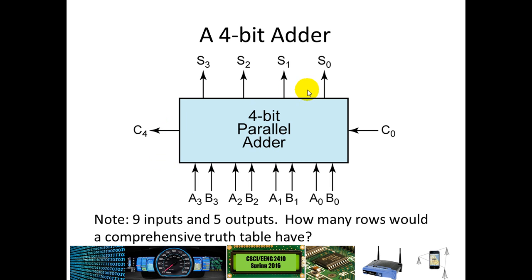So in that case, since we like to keep the same number of bits, we could really write this as 4-bit input, 4-bit output, and then if our sum was greater than that, we could call that a carry out, and then that could also be used to drive into a carry in. So if we were to put this in parallel and put it with another 4 bits, we could put these side by side to make an 8-bit adder and tie the carry out here, C4, into the carry in, C0. So we could actually carry values in and then carry values out.